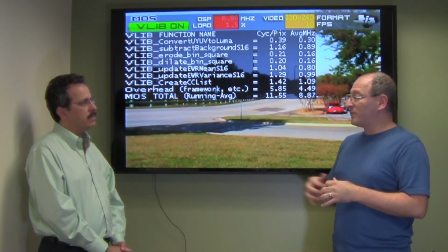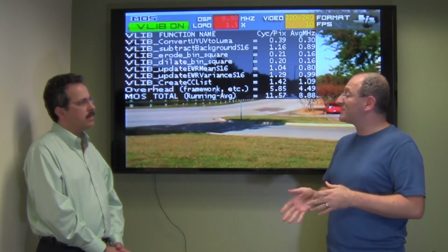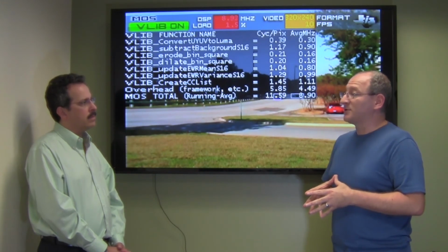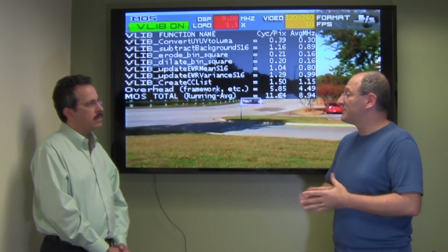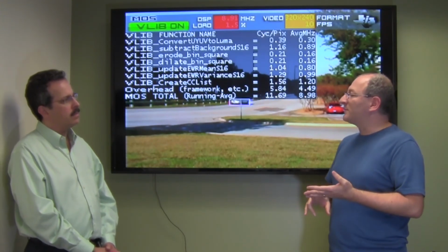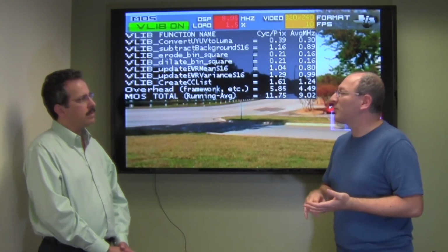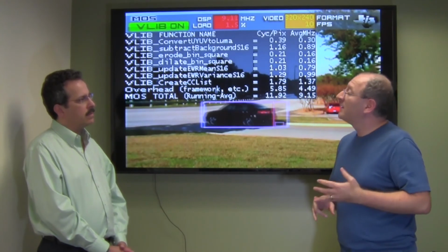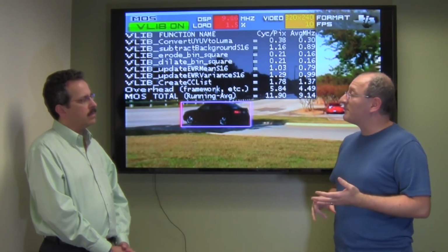And what's our last point here? It is the intrinsics, really. Intrinsics, so you are still writing C code, so there's no assembly going on here. And the compiler did all the register allocation for you. The compiler did the scheduling for you. So the tools have really come a long way.